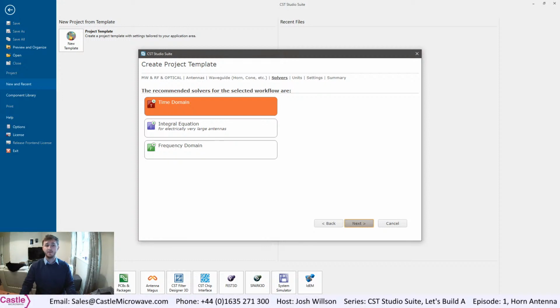The time domain solver, or transient solver in this instance, calculates the fields step by step through time by the leapfrog updating scheme. It is proven that this method remains stable if the step width of the integration does not overcome a known limit. This value of the maximum usable time step is directly related to the minimum mesh step width used in the discretization of the structure.